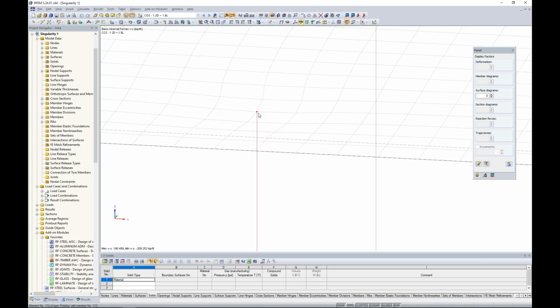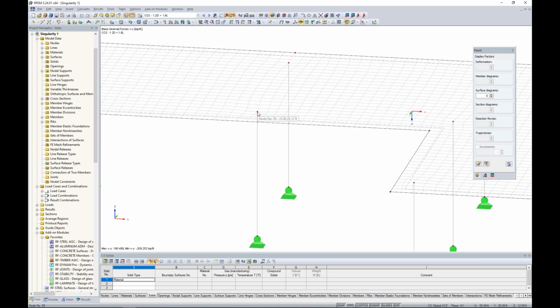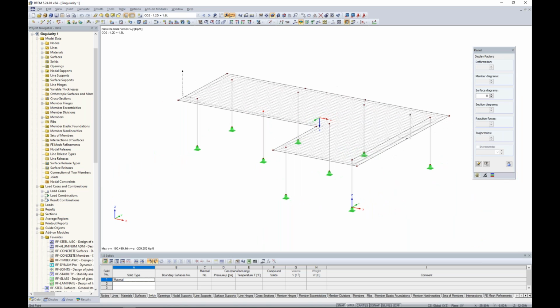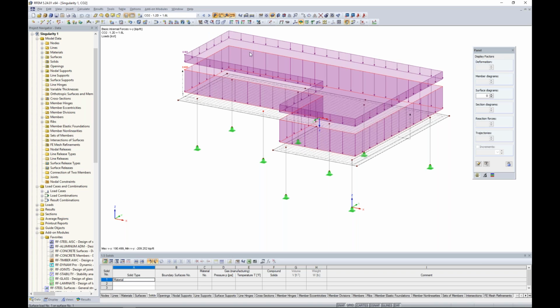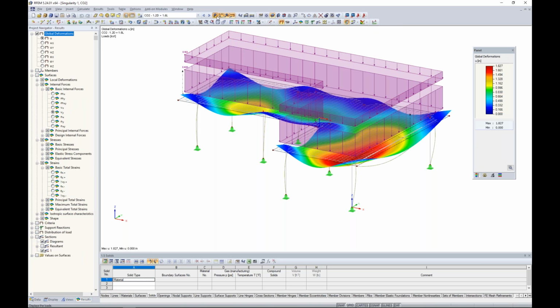So all of the force transfer is taking place at this single FE mesh point, and this is a result of why we get singularities, where we don't have really load distribution. So you can see for this example, what I've done is I've applied a couple gravity loads here for dead load and live load. And if we run the analysis, which I've already done in this case, and we take a look at our results, we'll turn on our ISO bands, turn off our loads.